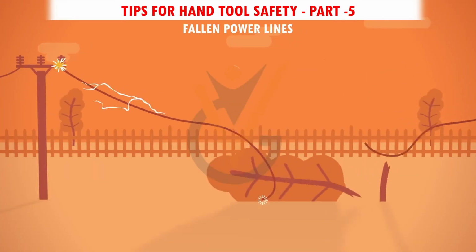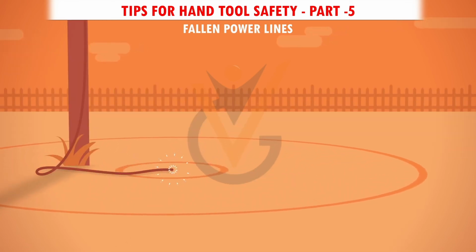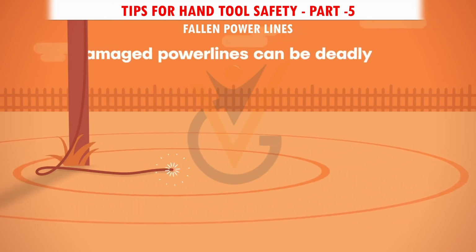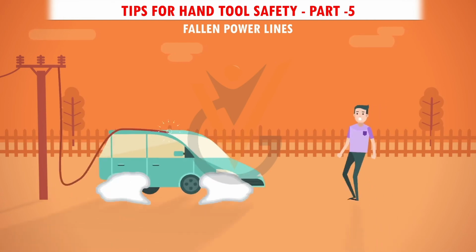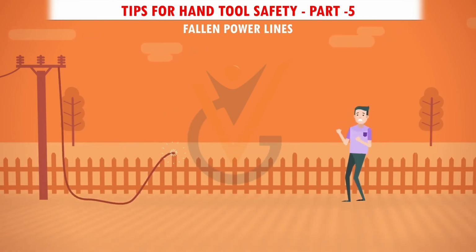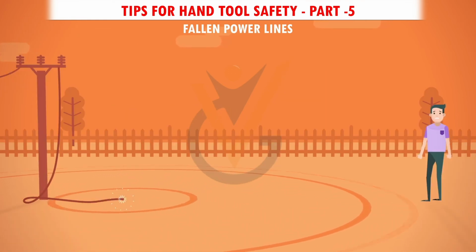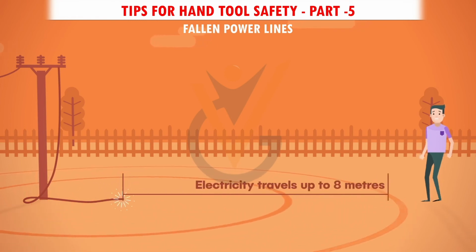Fallen power lines pose a serious threat to life and property, and so they should be dealt with extreme caution. If you are in close proximity to a fallen power line, follow these three steps. Stay at least 8 meters away. A fallen line may be live even if it does not give off sounds, sparks, or lights. To avoid any mishap, maintain a distance of at least 8 meters from the power line.